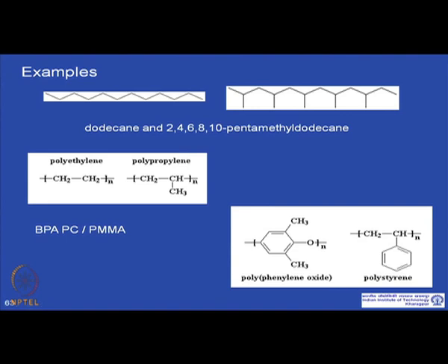So, basically to form a miscible blend, the molecular weight has to be low, which is not practical. So, for polymers which have high molecular weight, mixing is always governed by the enthalpy of mixing, and that has to become negative. There must be a specific interaction like hydrogen bonding or pi stacking or ionic interaction between the two polymer molecules.